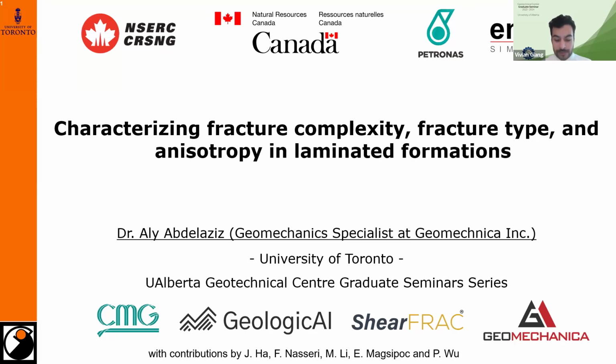The formation of fractures opening against the sigma 2 instead of the sigma 3 in the true-triaxial hydraulic fracturing experiment defies the dogmatic expectation that the fractures will always propagate against the minimum principal stress direction, the path of minimal tangential stress. The results are a clear indication that the tensile strength and anisotropy play an equally important factor to the in-situ stresses with respect to fracture initiation and propagation.